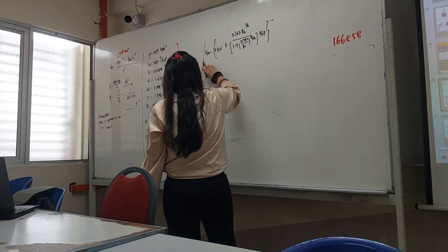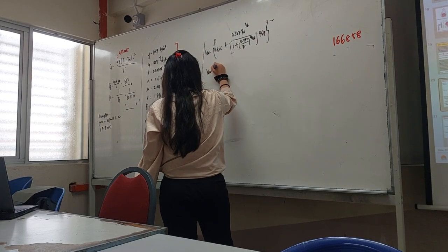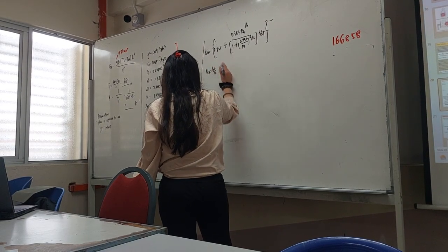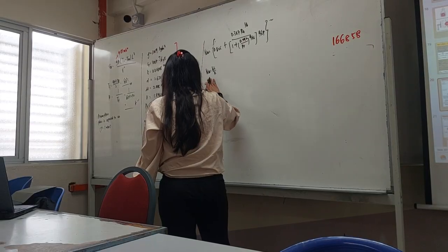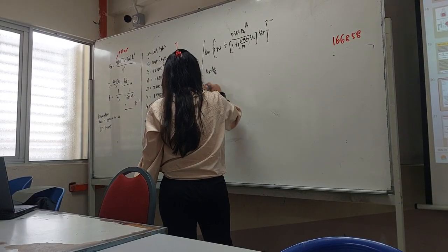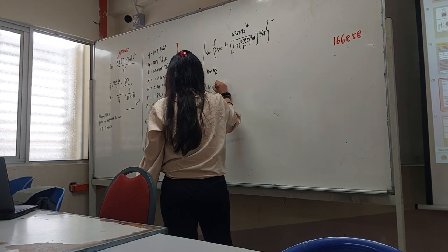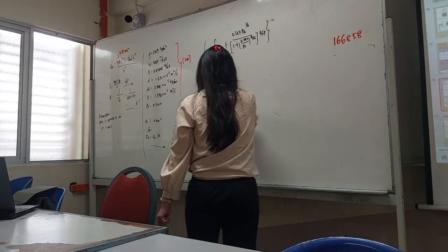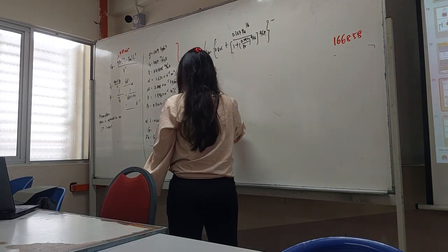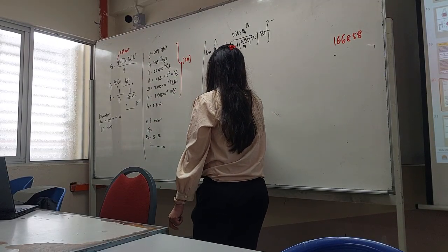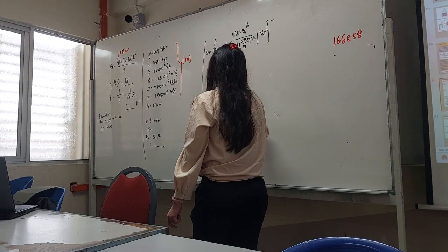Okay, so you know your Nusselt number equals hL over k, so you can get your h value. Get the h value already. If the question asks you to calculate the Q value, so Q equals hA(Ts minus T infinity).